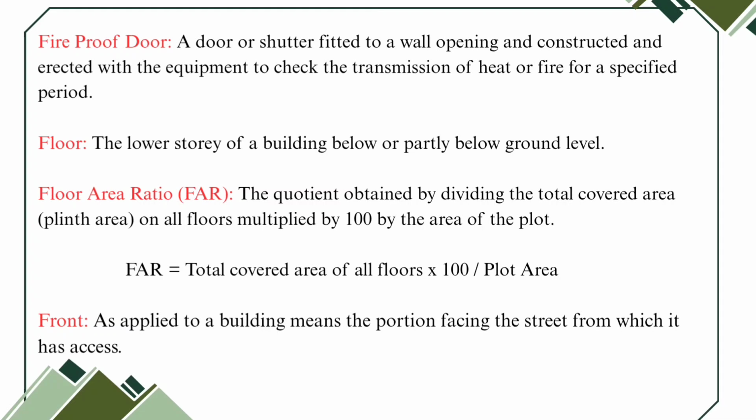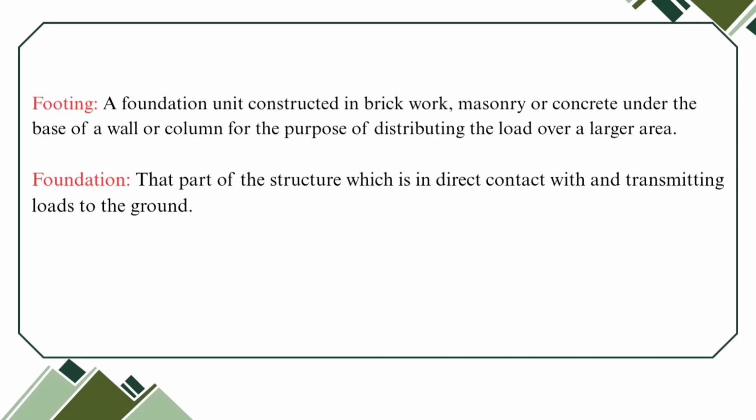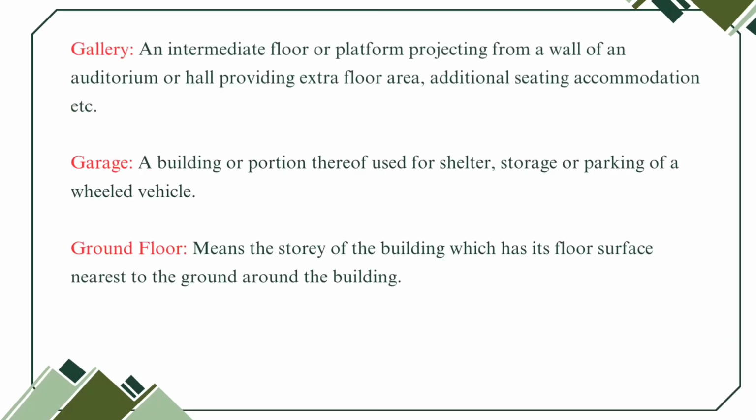Now the next is front. As applied to the building means the portion facing the street from which it has access. Now the next is footing. A foundation unit constructed in brickwork, masonry or concrete under the base of wall or column for the purpose of distributing the load over a large area. And the foundation means the part of the structure which is in direct contact with and transmitting loads to the ground. Gallery, an intermediate floor or platform projecting from a wall of an auditorium or hall, providing extra floor area, additional sitting accommodation, etc.